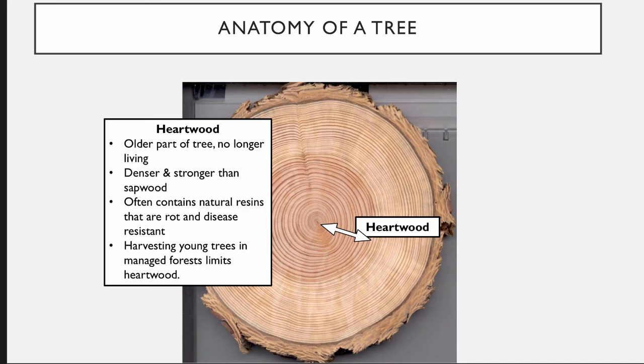The heartwood is also regularly gaining resins as it ages, and those resins help resist decay and insect attacks. You may have heard of things like cedar wood or redwood being great as an outdoor wood because it protects from insects and rot, but that's only true of the heartwood. If your lumber has sapwood, you do not have any of this protection.